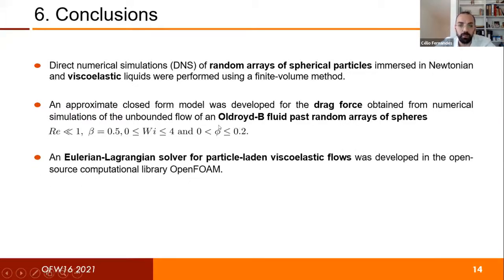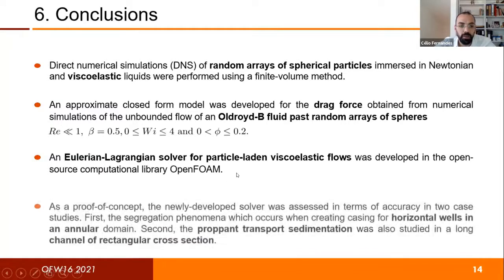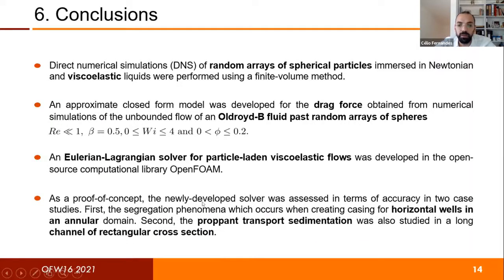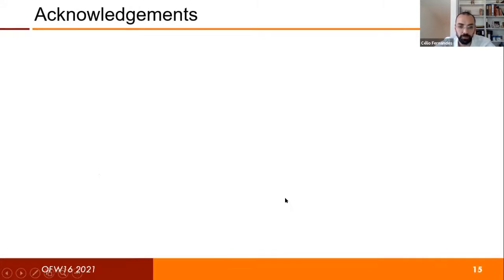Then this drag force model was implemented inside an Eulerian-Lagrangian solver, which can handle particle-laden viscoelastic flows. And finally, as a proof of concept, this newly developed solver was assessed for horizontal wells in an annular domain and for the particle transport and sedimentation in a channel of rectangular cross-section.